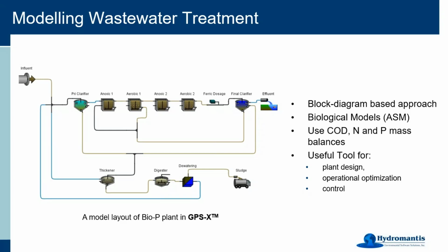So the outcome of this wastewater treatment plant modeling is the simulators that allow you to build block diagram based layouts for any given plant configuration, and then you can analyze those systems with different operating conditions and different inputs, and use this for either plant design or operational optimization or control. It has been quite a mature field, and there are several simulators in the marketplace, but this is quite limited to wastewater treatment plant simulations.